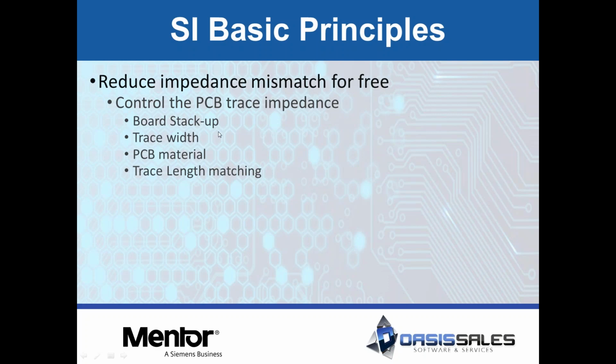So being able to analyze your board stack-up long before you ever go to the PCB design or produce even your first prototype. Playing around with trace widths to control impedance. Obviously, you need ground planes or some type of reference. I should say reference planes. I shouldn't keep saying ground planes, because it's really a reference plane, whether it's power or ground. The return currents are going to flow on each one. So playing with trace width to change the impedance of a line can assist with signal integrity and reflections.